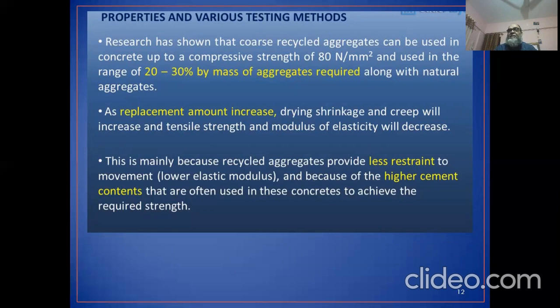In my experience, I've been working with recycled aggregate for some time as well. The maximum quantity we have gone is 30%. Beyond 30%, you will not get quality as good as you would like to have.